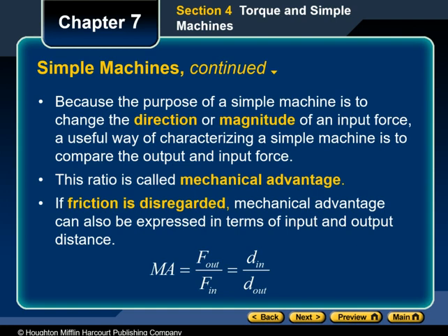by perpendicular distance out. The longer the input lever arm as compared with the output lever arm, the greater the mechanical advantage is. This in turn indicates the factor by which the input force is amplified. If the force of the board on the nail is 99 newtons, and if the mechanical advantage is 10, then an input force of 10 newtons is enough to pull out the nail. Without a machine, the nail could not be removed unless the input force was greater than 99 newtons.